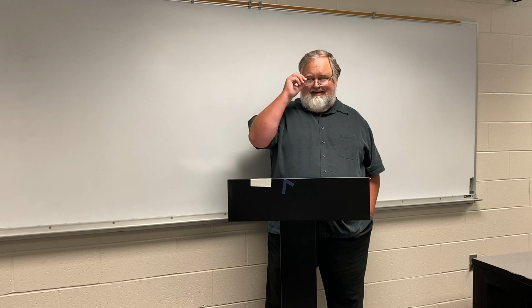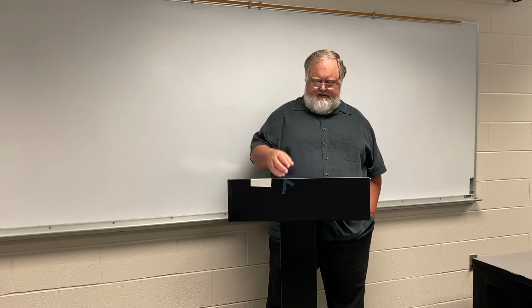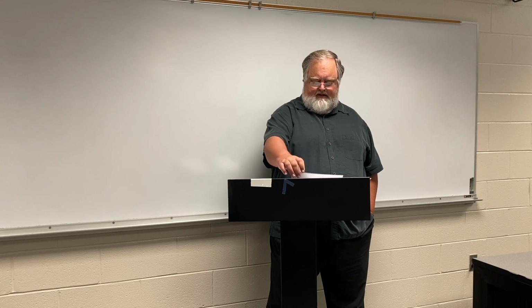I'm going to say a standard door is 80 inches, so that's what I'm going to go with. The distance from the toe of the staircase to the bottom of the upper level needs to be at least 80 inches. Again, there are people, Shaquille O'Neal, whoever's over 7 foot, who have to duck. But for most people, that 80 inches will be fine, yes? And then you have the total rise, which is the total distance from the floor you're leaving to the finished floor you're going to arrive at.